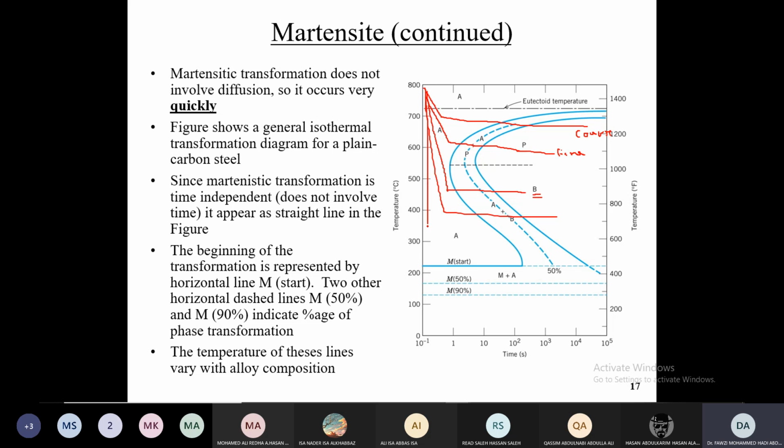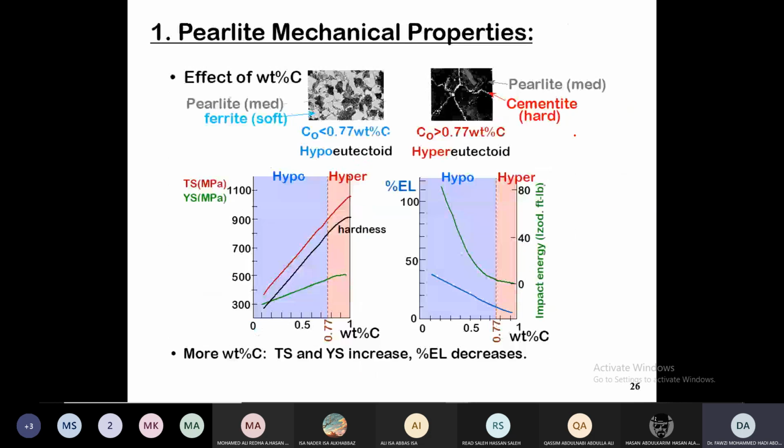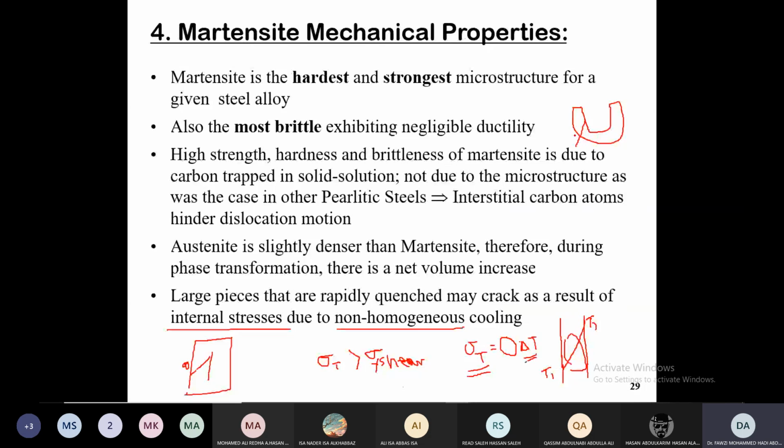For the martensite, you jump with the temperature there to temperatures at the room temperature, to produce the martensitic structure there. This is what we are saying. So in the case of pearlite, you are having slow cooling, you could call that normalizing, meaning leaving it to cool slowly. You will be producing the pearlitic structure here. And going back to what we were saying here.